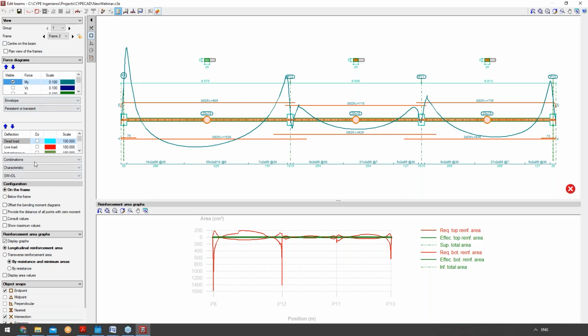Of course, you can see I have some specifications that I'm able to do. I can view my moment, my vertical and horizontal forces inside the editing of this beam as well. Also looking at the different combinations and envelope load specifications that I've set. I can view those here as well, and also some bending moment diagrams inside the program. I can also look at the addition of reinforcements. So I can introduce assembly reinforcements, additional reinforcements, and skin reinforcements into the structure here.